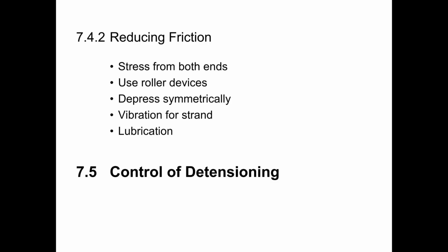But I agree that after the drape strands have been tensioned, if we go out there and start banging on the strand in the middle of the bed with a hammer to vibrate it, that may help to equalize the force in the strand. Or if we tap the strand with a concrete vibrator, that may help to equalize the force in the strand between the ends. But in practice it doesn't sound like something that I would want to do or recommend that someone else do. And then lastly is lubrication.